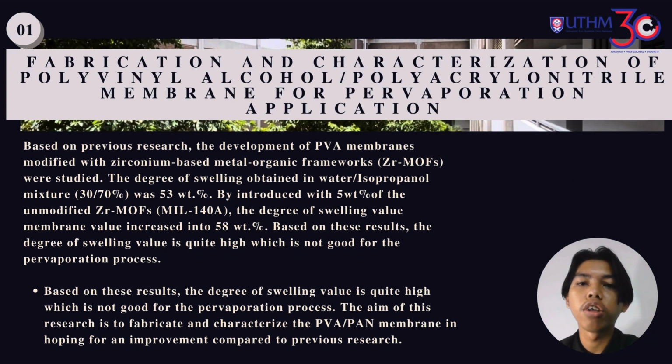So for our Polyvinyl project, the title is Fabrication and Characterization of Polyvinyl alcohol with Polyacrylonitrile membrane for Pervaporation application. Based on the previous research that we studied, for example, the development of PVA membranes modified with zirconium-based metal organic framework, ZrMOF, the degree of swelling for only PVA membrane in water isopropyl H2O obtained was 53%. By adding the unmodified ZrMOF, the degree of swelling value increased to 58%.